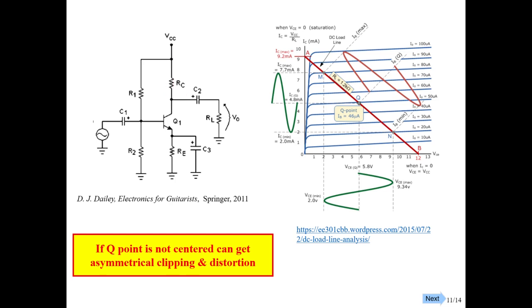So what ends up happening? Well, there's going to be some point where you make the input current large enough, and it's just going to go beyond where this thing can operate. And that's what's known as saturation. That would be the largest current that we can have flowing through here. Can't get any more, no matter how far up we go putting more IB in, we can't get anything more out. And then as IB gets smaller, we're going to reach a point where we have cutoff. And so now the current just stops.